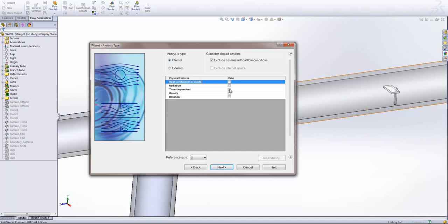And if we conduct an equilibrated or a normal flow analysis, these structures will become a blur because the results will be averaged so that we have a convergence. Whereas with a time-dependent study, we can see how those structures move downstream with respect to time.